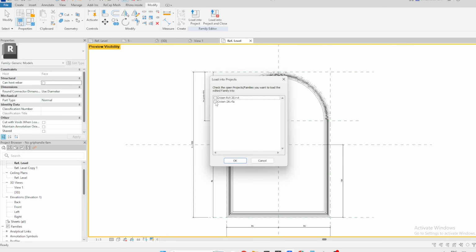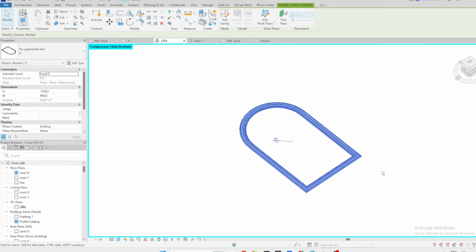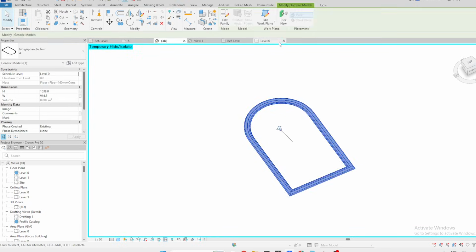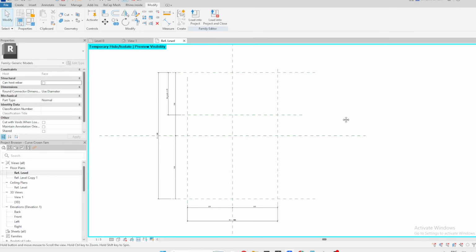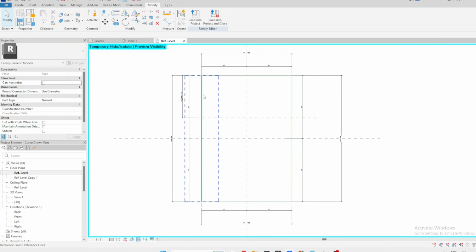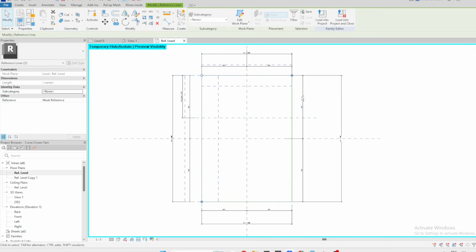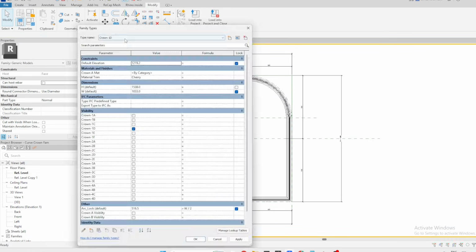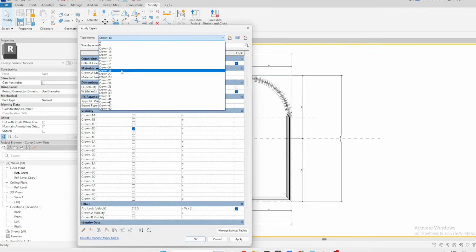Standard reference planes don't give you 3D grip handles for a Revit family. To fix that, I built the framework using reference lines and reference planes. This keeps width and height as instance parameters with active 3D shape handles, making it effortless to pull, stretch, and align the trim directly over point cloud data in scan-to-BIM projects or adjust it during conceptual modeling. Once the base geometry worked, the repetitive hurdles began.